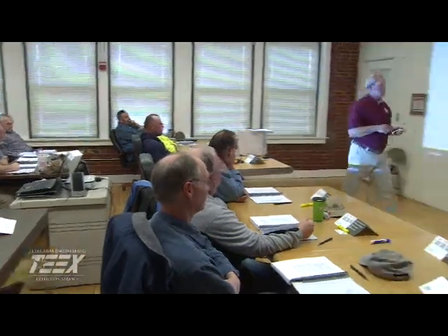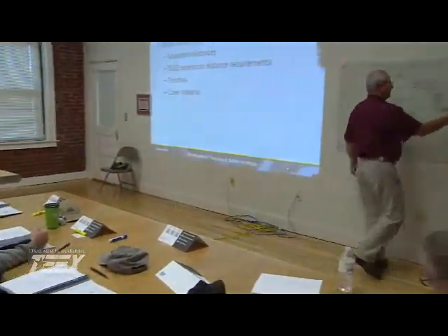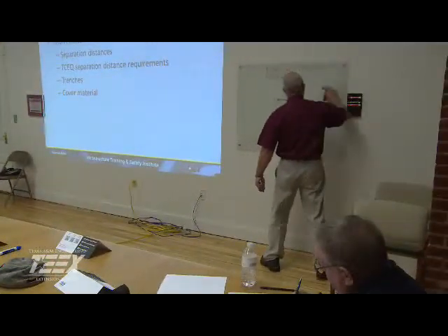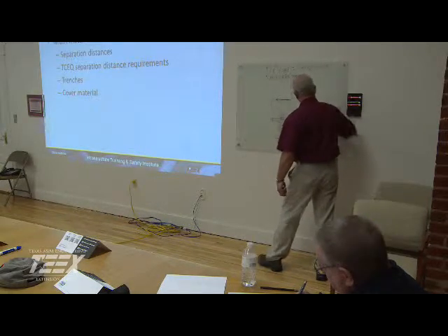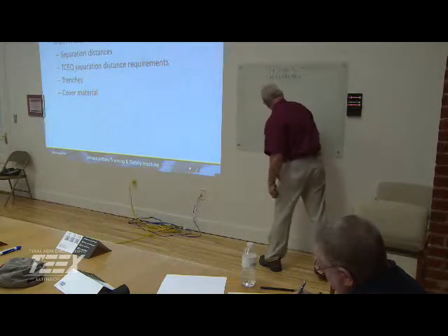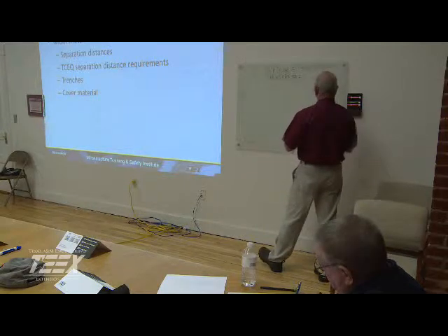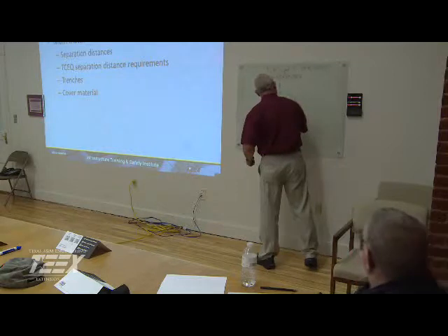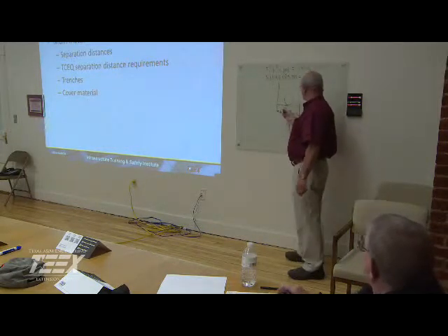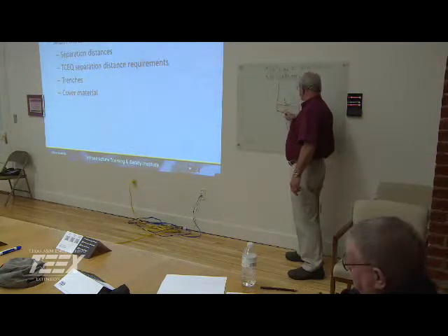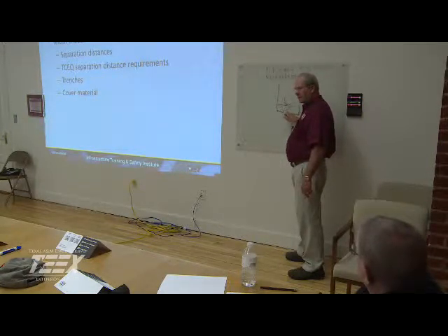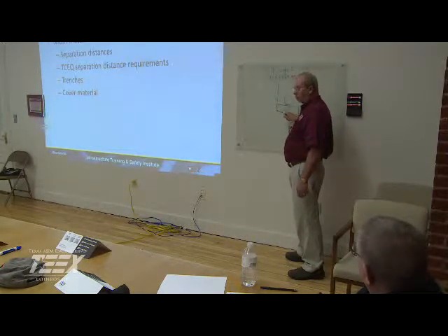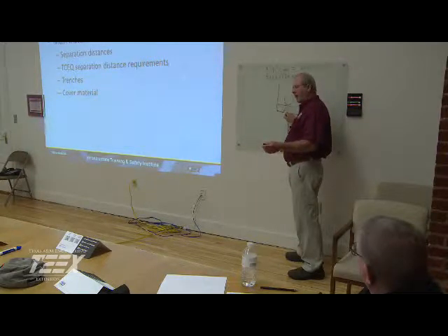Trenching and proper trenching. And I'll just give you an example. Each AWWA and ANSI have some really good standards, but normally your trench, if I'm setting a pipe in here, the AWWA wants you to have 6 inches of select material. In Texas, we can go as little as 4. It can be 4 inches or 1/4 the diameter of the pipe, whichever is greater.